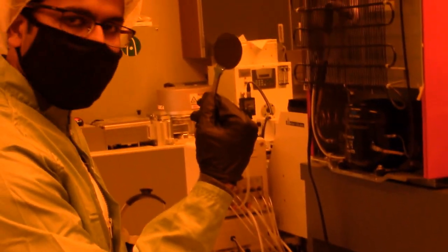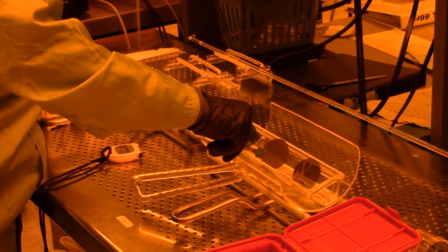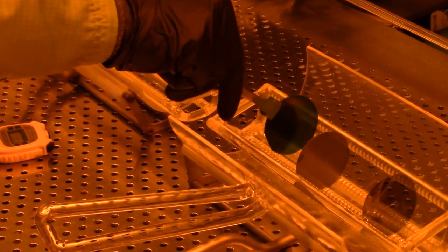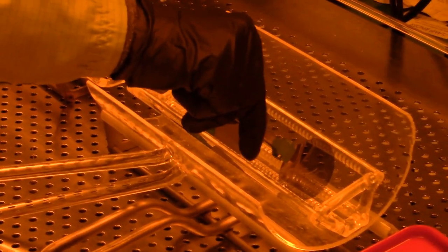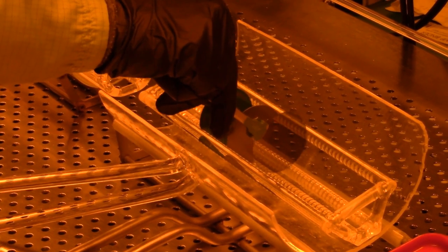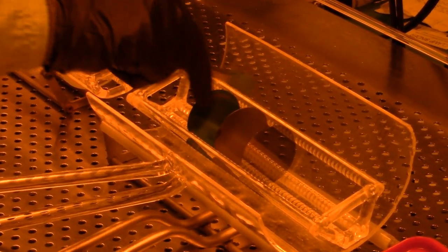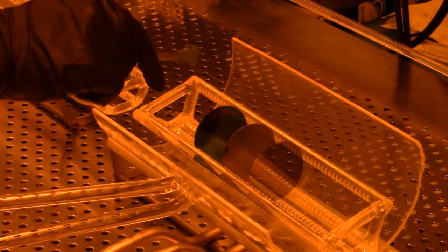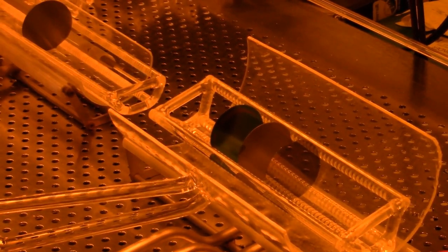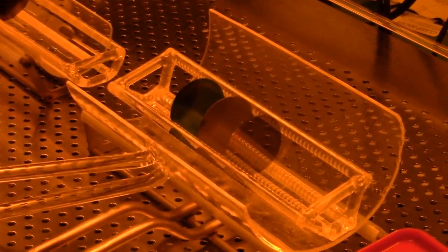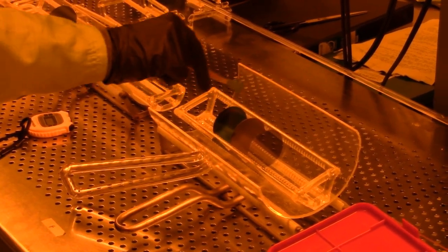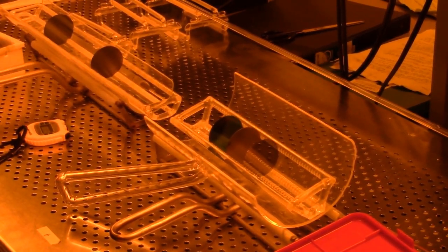The RCA clean 2-inch wafer is kept somewhere in the middle of the boat. There are wafers called dummy wafers that are kept in front and back of the actual wafer that we'll be performing oxidation on. These wafers are to make sure that the gas flow is streamlined rather than turbulent, so you have an even growth rate of oxide throughout the entire wafer surface.